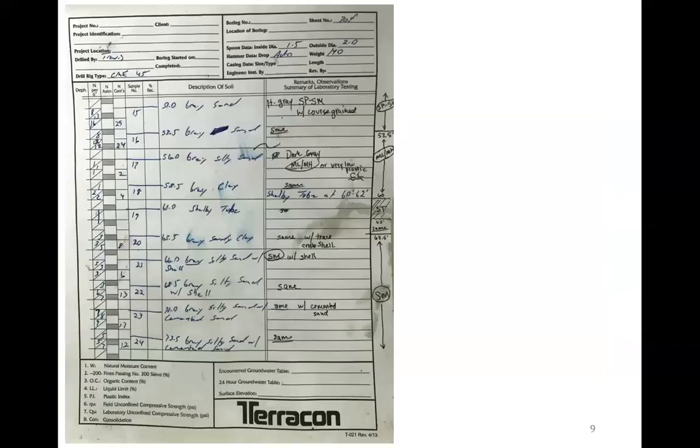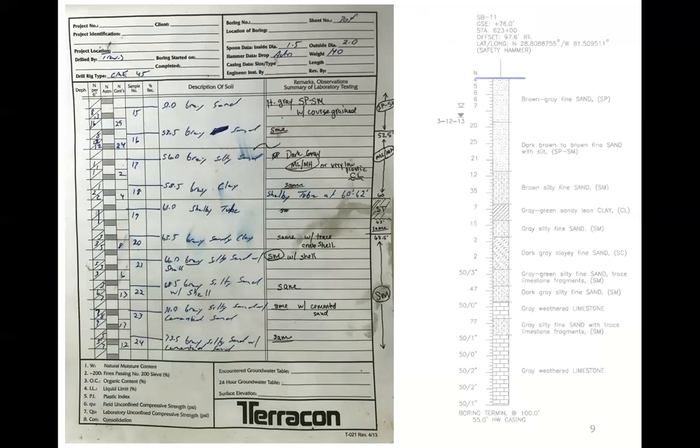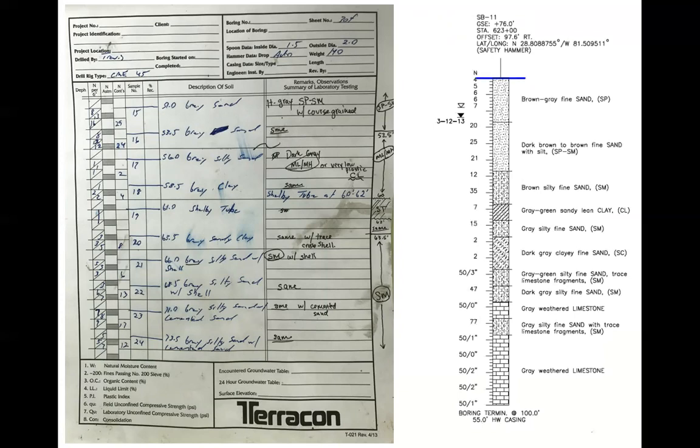So what the results will actually look like is something like this. This is actually one of the reports I did a long time ago, but I don't know if you can read any of that stuff, but if you can't, it's okay because nobody else really can. The drillers have their own way of marking all these things, but then the goal is to take this and turn it into something that we put in the report. So these N values right here, these are those N values. These are the blows per foot. If you look at your slides, those are shown right here in this section.